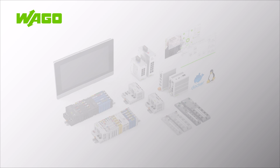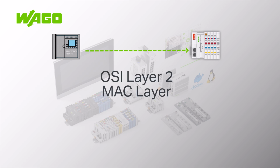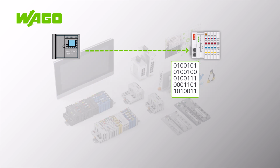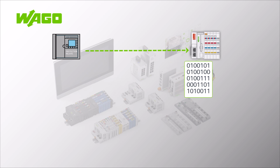A special feature of IEC61850 is the Goose protocol. The Goose protocol is used in particular for protection devices to send fast and reliable messages, operating at OSI level 2. That is the MAC level. The Goose protocol ensures messages are received by sending them multiple times with increasing intervals.